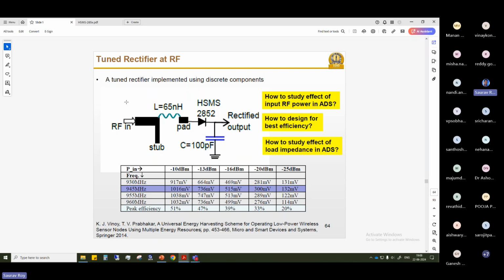Okay. Now the simple LC circuit, as you know, you can implement in microstrip as well as with components. Here the capacitor has been implemented by an open stub, but L has been taken as a lumped element only. Why a lumped element? As I told you, we have seen this before, it might not always be feasible to replace it, because the line might be very thin or very wide. In both of these cases it might not be possible, so you have to use a lumped component.